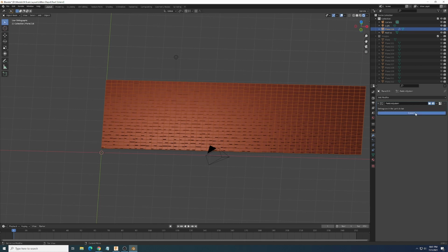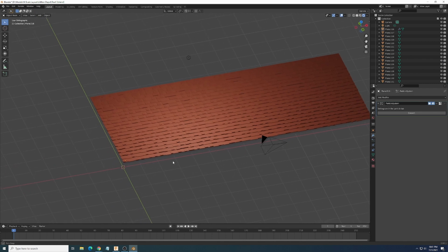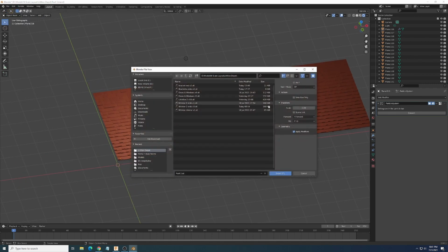Set the scale to 1000. Units aren't a strong suit of Blender. It seems to export as unitless units. My printer defaults to millimeters, so if you design it in meters, setting this scale to 1000 makes it all copacetic.